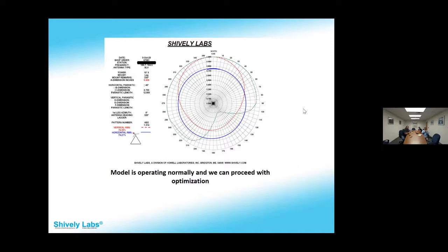And the outdoor ranges have a noise floor too, where something like HFSS doesn't. So you end up with a noise minimum, and you can only measure, I think ours is 40 dB, which is really good. But if we were to try to do a front to back ratio of 50 dB, we couldn't do it on this range. So I'm not sure who could. Well, so that's like when you're looking at just the return loss or the VSWR. 20 down is pretty good. 30, gee, that's nice.